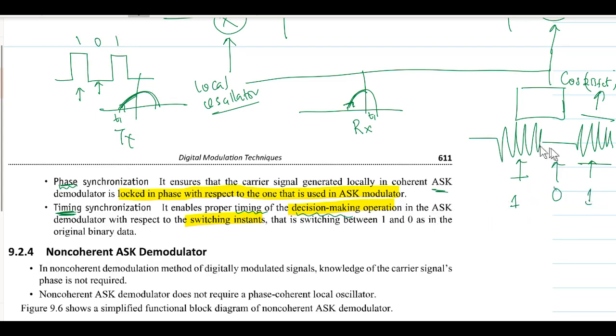But in the event that we have mismatched instances, I want to use a different color. We have mismatched instances. Probably at this point, the time at which we are switching our demodulator to detect the signal might be late by some time tau. If tau is in the range of, or bigger than, probably half of the period TB, there are times when we might realize that we have sampled a zero whereas a one was transmitted. And then we might sample again at this time and still receive a zero because there is some delay that is causing us to have